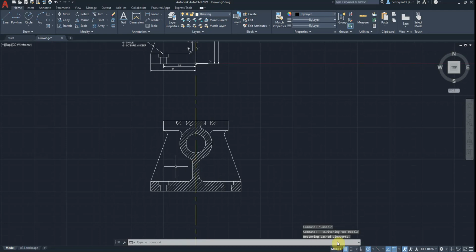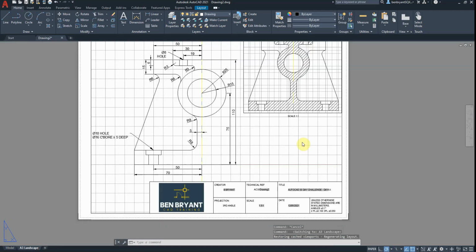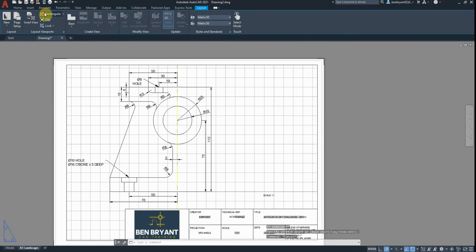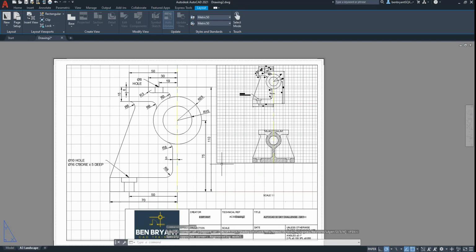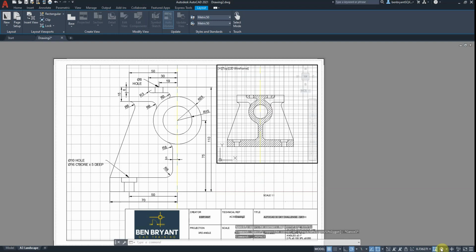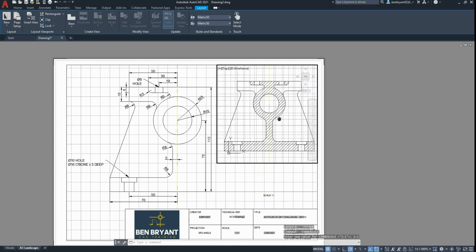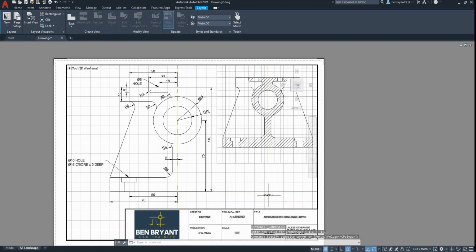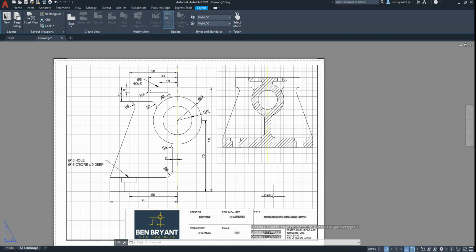If it's 1:1, the best thing to do is, rather than putting in a view like this, just drop that down out of the way and do the actual viewport. So put in a secondary window, something like this. Then you can pan, and set a proper scale. So that one there is an official 1:1 scale. Okay, so that's a nice piece.